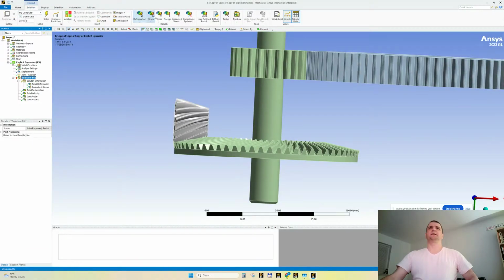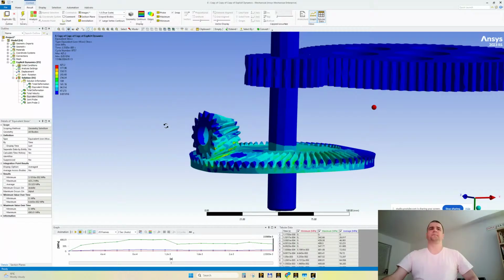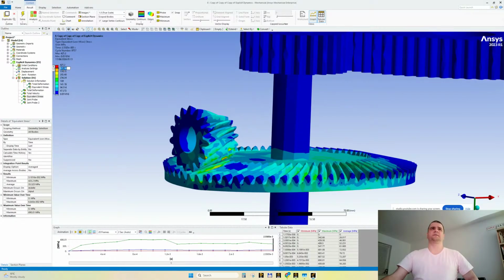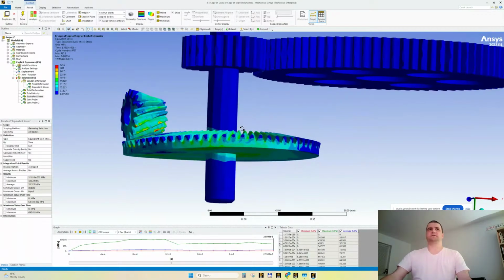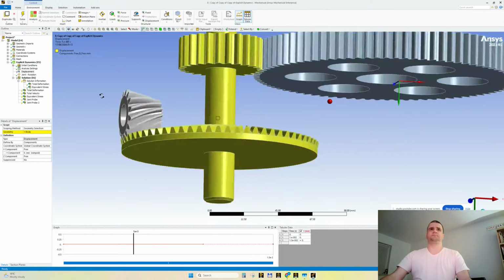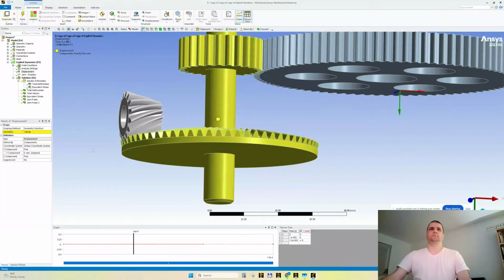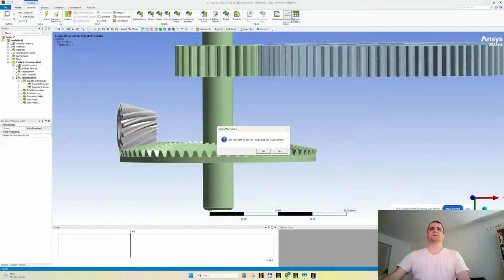Let's assign a permissible stress solution. So look at the values. Nice values, yes? So 300. Nice values, yes. What we need to do now, if possible, is the last thing. Let's assign on this face zero displacement. Yes? Zero axial displacement. Let's see if it works.